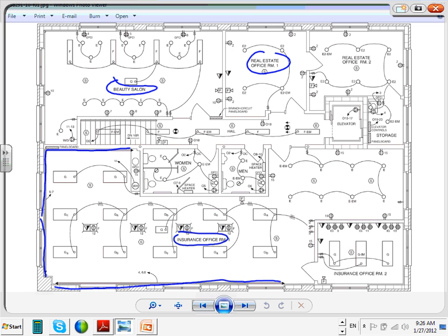Tao, because you and Ashley are so good with Revit, I want to remind you something for next quarter. We're not using a multi-outlet assembly this quarter. Next quarter, we're going to have a multi-outlet assembly exactly like this one, and you guys are going to grab one and put it in Revit. The family that we have right now in Revit, you're going to drop it, and it looks like this. You grab one end and stretch it to match how long you want it to go. So that's the family that we have. Please pay attention to the circuit that's coming out of it. We're not doing it now, but we will. It's fed from all these circuits. That's what I want to bring your attention to.